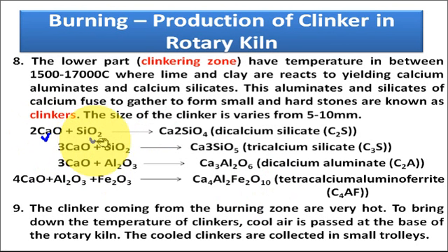They react in different proportions and form various types of calcium silicates and calcium aluminates, like dicalcium silicate Ca2SiO4, tricalcium silicate Ca3SiO5, tricalcium aluminate Ca3Al2O6, and tetracalcium aluminoferrite.